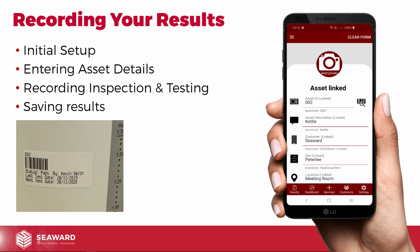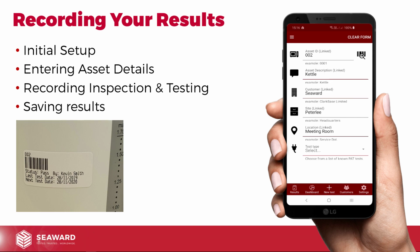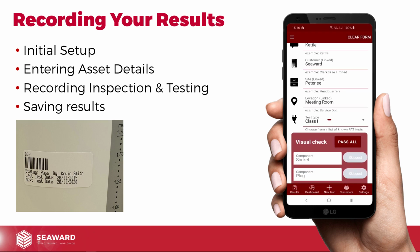What was it? It was a kettle. And the customer was Seaward. The site was our office at Peterlee. It was in the meeting room, and then all I need to select here really is the test type. The test types we've got on here are class 1, class 2, a lead test, an RCD test, or a visual only. So this is class 1, so we select that.